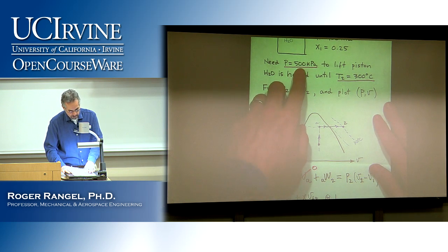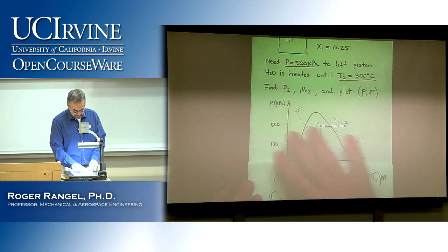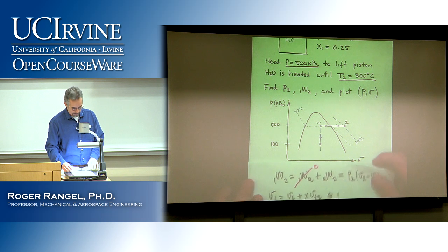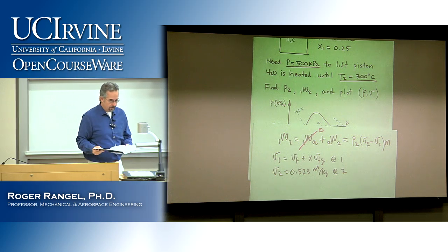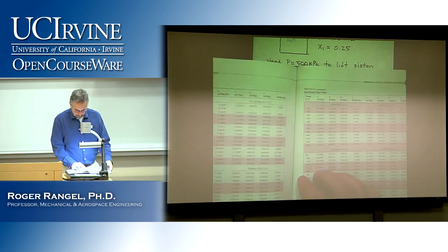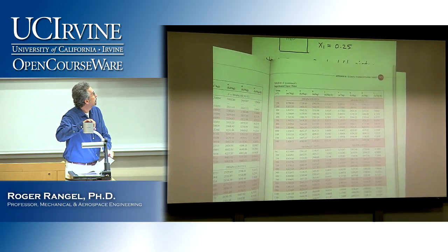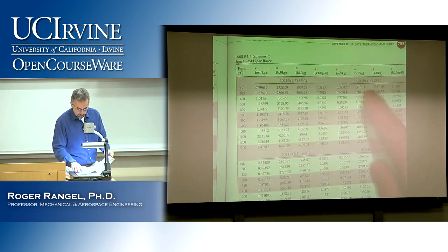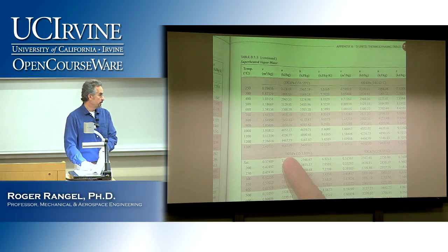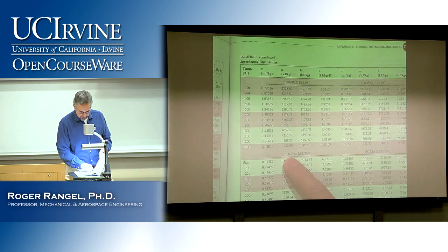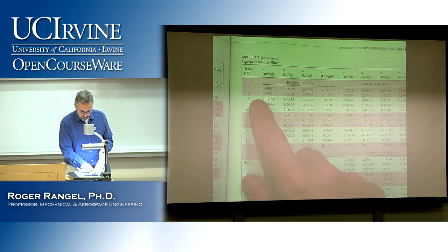So suppose this pressure had been 450, he's saying, instead of 500. Everything is the same, right? The only thing that changes is this last calculation. So I would have to go here and see that I have a table entry for 400 and another one for 500, but I don't have one for 450, right? So I do have the temperature of 300 in both cases. Right? So what do I do in this case?